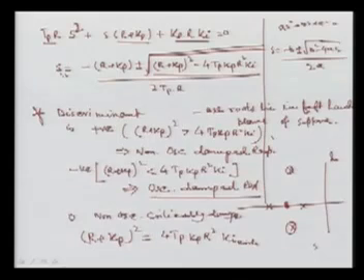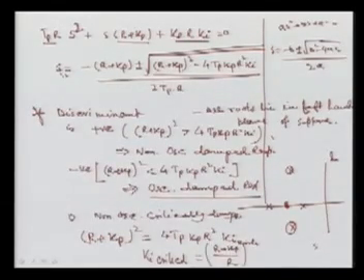If we divide, we can write Ki critical equal to ((R plus Kp) divided by R) square, times 1 upon 4 Tp Kp. This is the critical value where we get the non-oscillatory critically damped response.